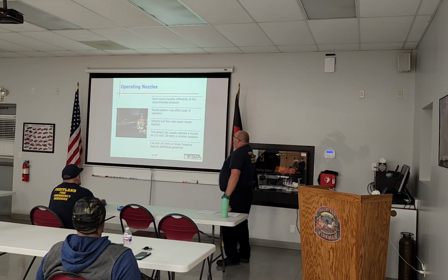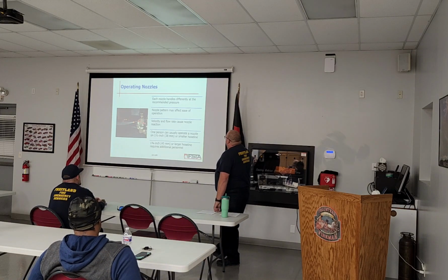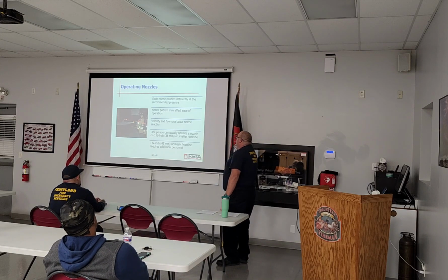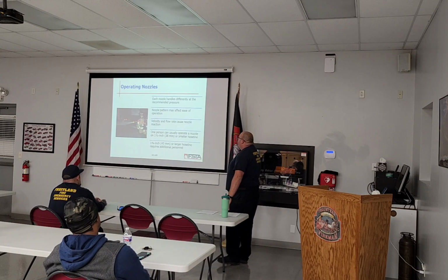All right, operating nozzle. Each nozzle is handled differently at the recommended pressure. Nozzle patterns may affect ease of operation. Velocity and flow rate cause nozzle reaction. One person can usually operate a nozzle on an inch and a half or inch and 3/4 or smaller hose line. Larger than inch and 3/4 hose lines require additional personnel.